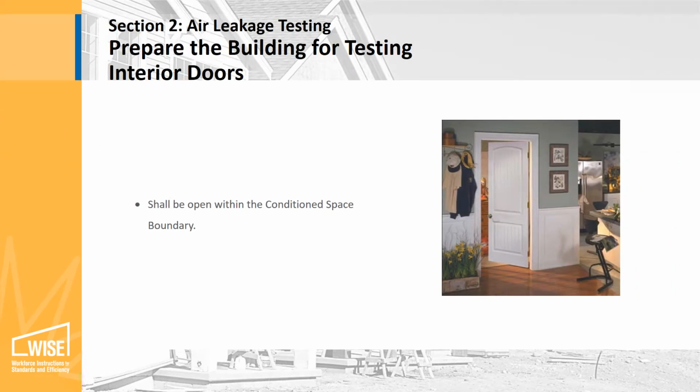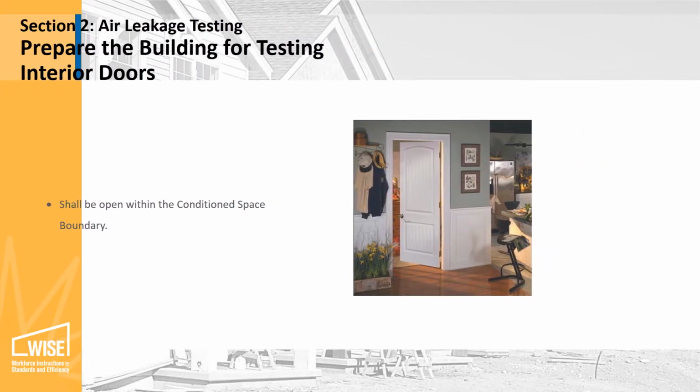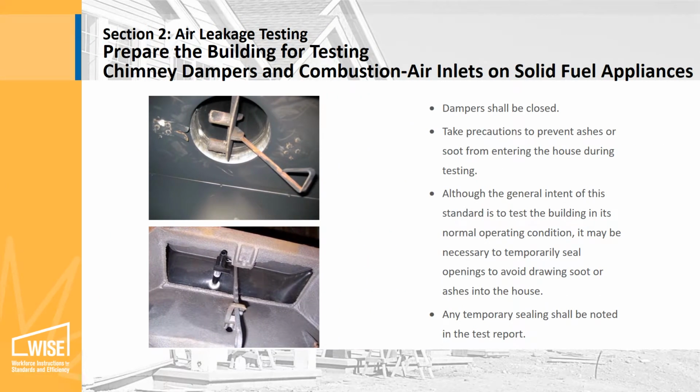Interior doors shall be open within the conditioned space boundary. Chimney dampers and combustion air inlets on solid fuel appliances should be closed, as that is the natural condition.